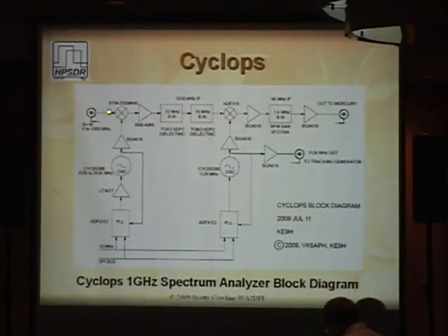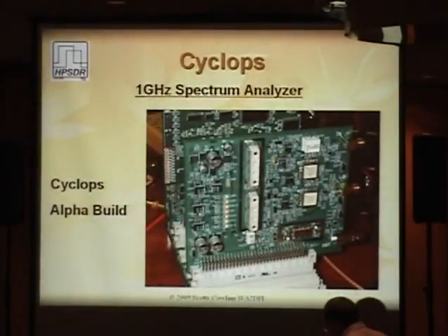So you can see the first mixer here, second mixer here. It's your buffered output, oscillator output. And that's a picture of it. Notice the shielding traces around. I think this is the IF amplifier here. This is the LO buffer, and these are the two filters.